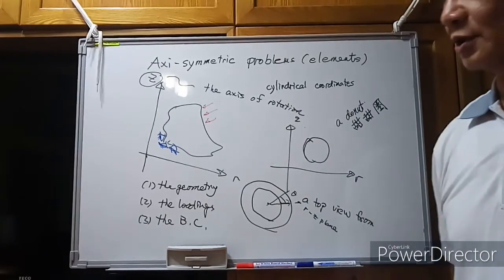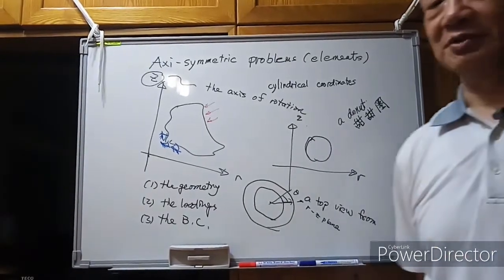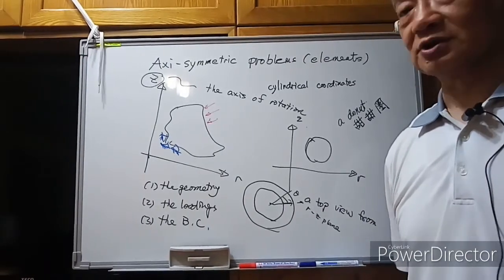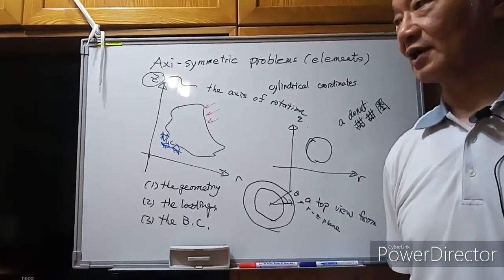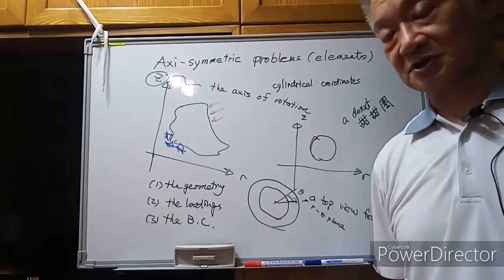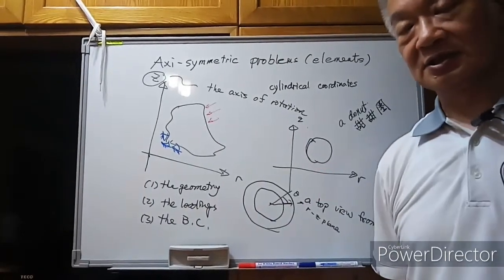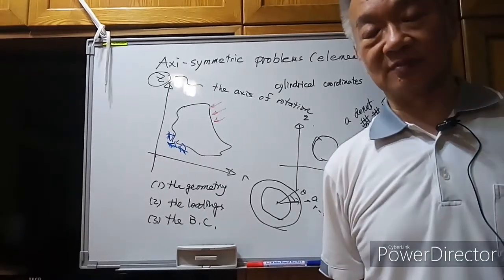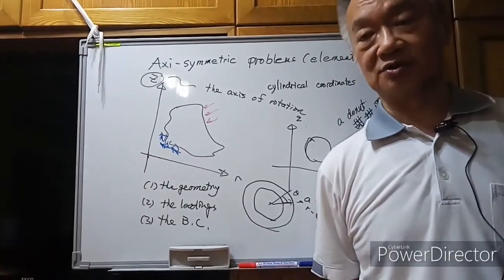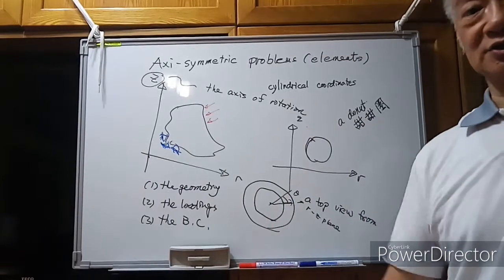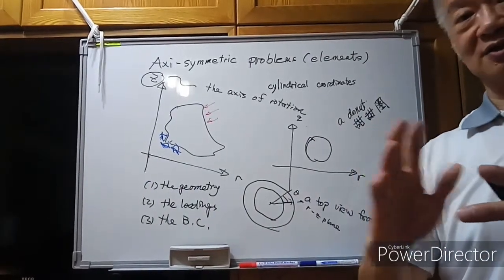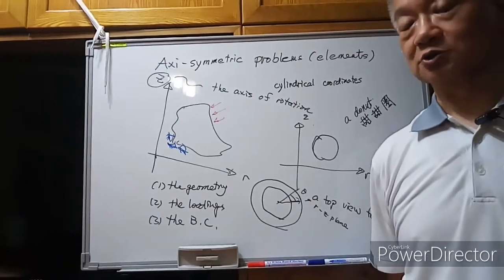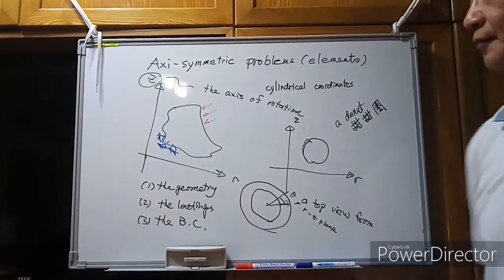And also remember that all structural models have simplified assumptions. In real structures, it is very hard to find anything which is exactly the same as the assumptions of the structural model. There is always something a little bit different between the real structure and the structural model.